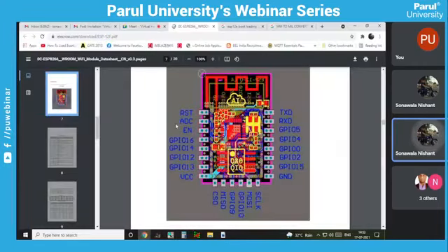Now on the right hand side, we have another 8 pins, but we are not numbering them as 15 16 17. We will start with 22 21 20 19 18 17 16 and then 15. Why? Because as we can see, RST to VCC is 1 to 8, right? CS0 to SCLK is 9 to 14.